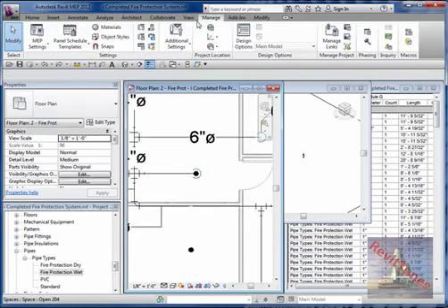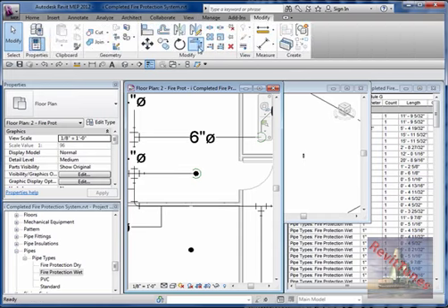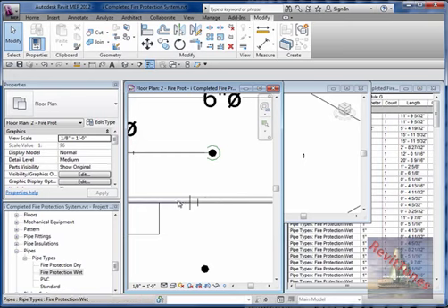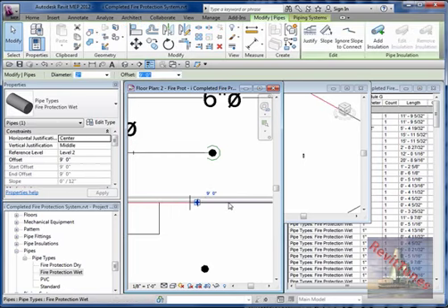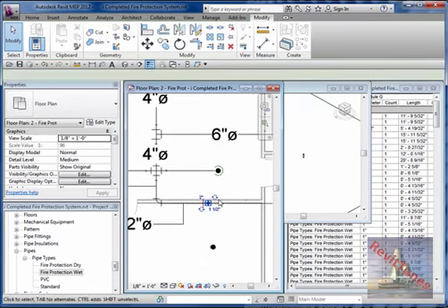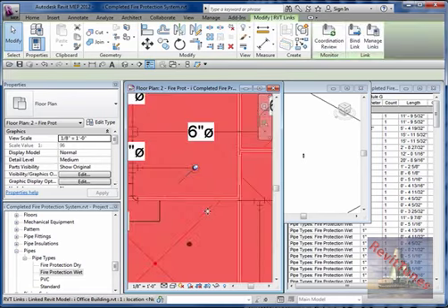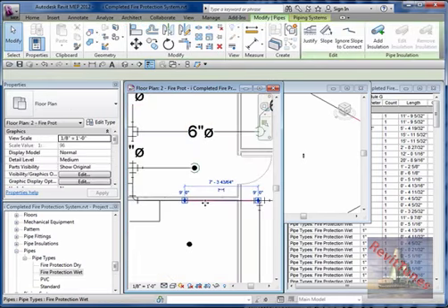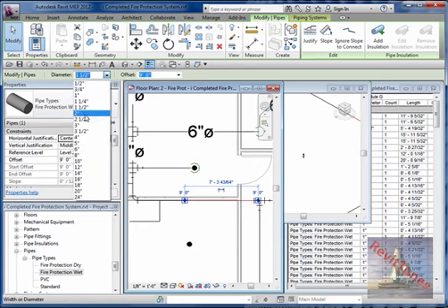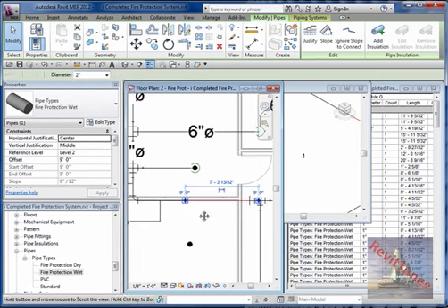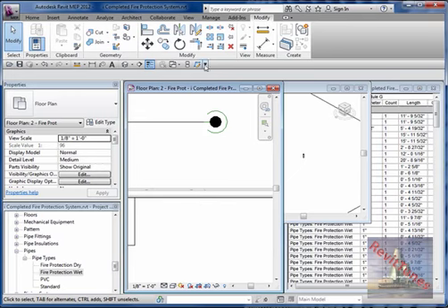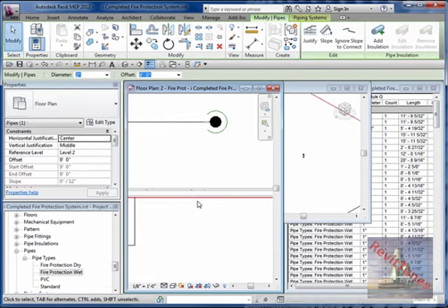Manage, modify. I'm gonna use... oh, I see, because we had two diameters, and this is 2 inches, this is 1.5. So first I will put it in the same diameter, 2 inches also this, and then we change it after we connected it. So I want to make it the way it was in the past. Okay, so it's 2 inches.